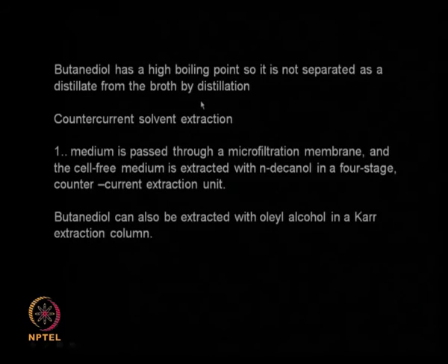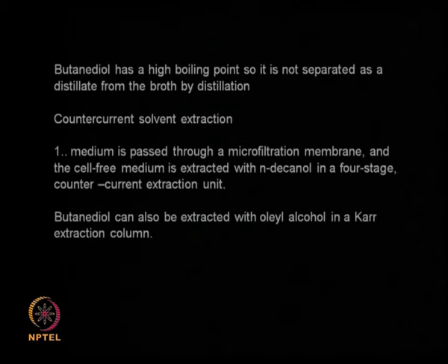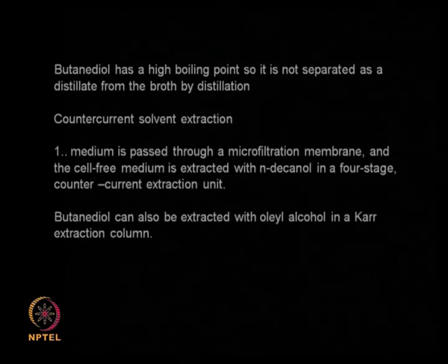So, butanediol has a very high boiling point. So, you cannot use a distillation column and hope to get butanediol at the top of the distillation assembly. So, that is the main problem. So, extraction is the only way of extracting butanediol after the fermentation.